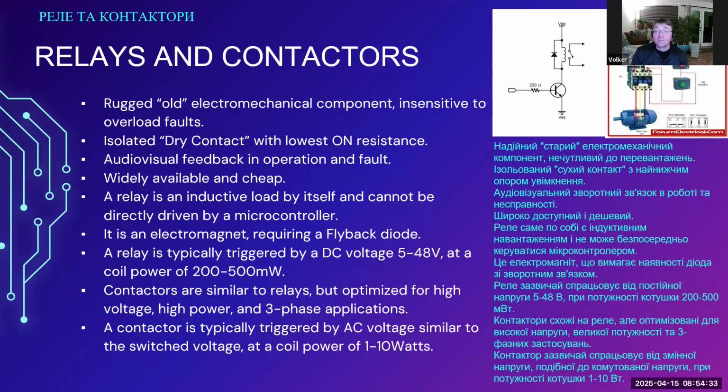Generally, if you want to switch a contactor from a microcontroller, you will have to put some form of relay in between. This could be a solid-state relay. However, you cannot drive a contactor directly from a microcontroller, not even with a transistor in between. You can switch a relay from a microcontroller if you use a transistor or a MOSFET.